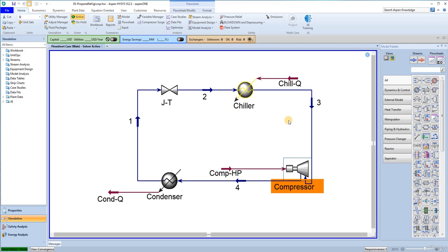Now to our third task, customizing the HYSYS workbook. Aspen HYSYS allows you to customize the workbook view in several different ways. You can add additional pages, change the variables that are displayed on the current page, or change the format of the values. In this task, a new workbook tab containing the stream properties, molar heat capacity, mass heat of vaporization, and mass density will be added.